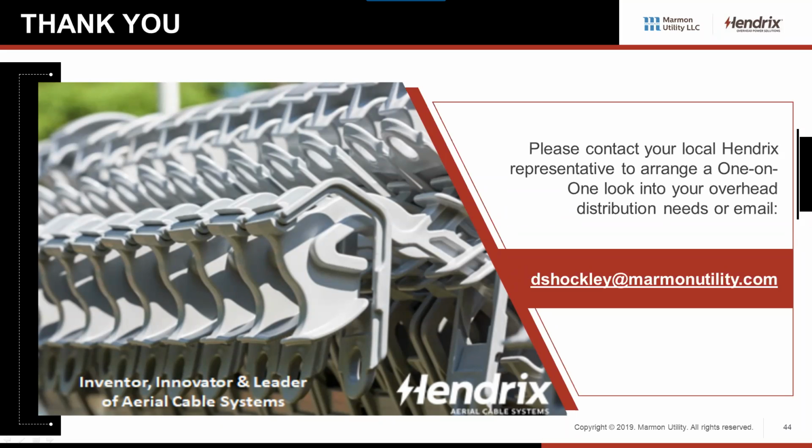Yeah, and if I could add to that, Ted, one of the arguments from the fiber manufacturers is that I'm not sure if you're going to hang a massively heavy system on there and bend the tube and damage the fiber and prevent the light from getting through. In reality, we've installed thousands of miles with OPMW, optical messenger wire, with the fiber in that messenger, with 35 kV, and I mean shockingly heavy conductors, 795, 954, 1033, 1272, 1351, and we have never had a problem. So that's one thing on the 35 kV, really heavy stuff.